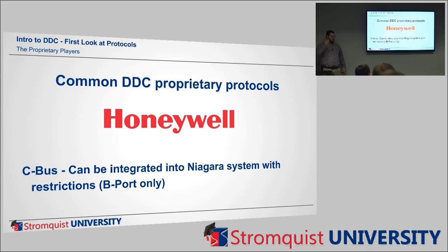But the key is to always be moving more towards the open, and that's what Rob was talking about. Always say I want fully open JACEs. I want stuff that anybody can work on. Maybe not so much anybody, but maybe more than one option. If you have a Johnson Controls controller that goes through their Tritium side, through the contractors, well, maybe a Honeywell contractor doesn't have the tool set to reprogram that, but you've got 10 Johnson contractors within distance of you that can come in and work on the system.